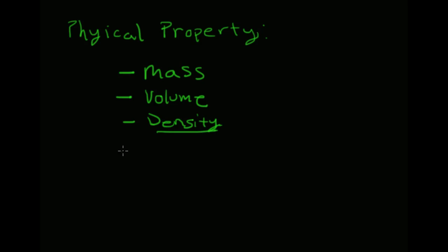But density can ask questions about buoyancy. If the density is less than 1 gram per cubic centimeter, then something floats in distilled water. If it's more than that, it sinks. So these are things that come up. And a physical property also includes color. The color of something is a very physical reality. It's an optics kind of thing. So sometimes color matters in your design. So color is a physical property of a material.